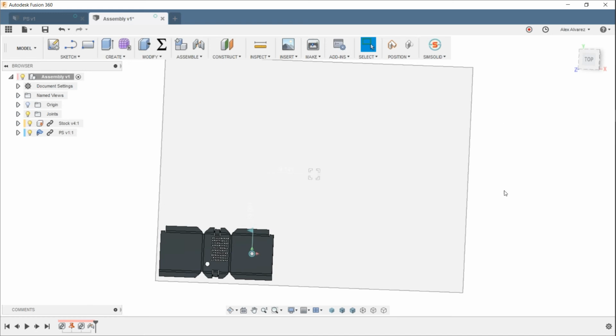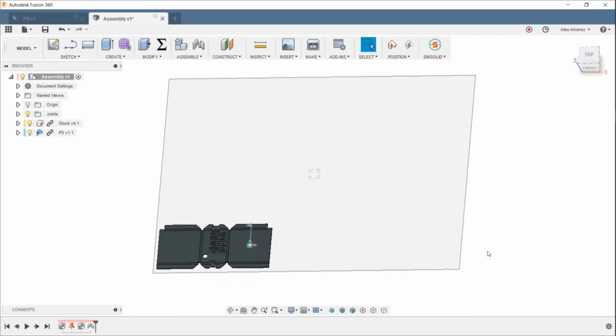There aren't features that show you the waste material, or that automatically place your parts or your components at a specific angle to minimize waste. You do have to do that yourself. So I just wanted to make that clear. There is some manual labor that has to go into this when it comes to actually adding your components to it. So we place the components roughly in the position that I want to start in.